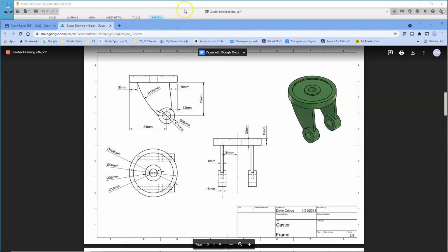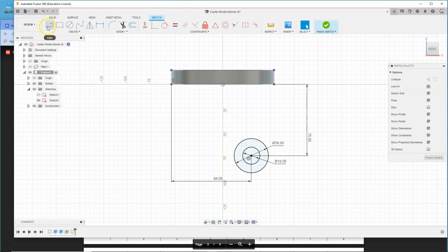So we'll go ahead and do the straight line. Let's come over here on the right side of the circle, and it's off to the left a little bit. So I'm going to start my line tool. I'm going to have it snap to the circle somewhere over here on the right hand side. And instead of going straight up and being vertical, I know it's kind of angled. And I don't want to snap it right there. That's in line with the center. I'm going to do it really wrong. You don't want to snap it to something, because once it snaps to something, it's going to stay there. So I'm going to put it on this bottom and just leave it be.